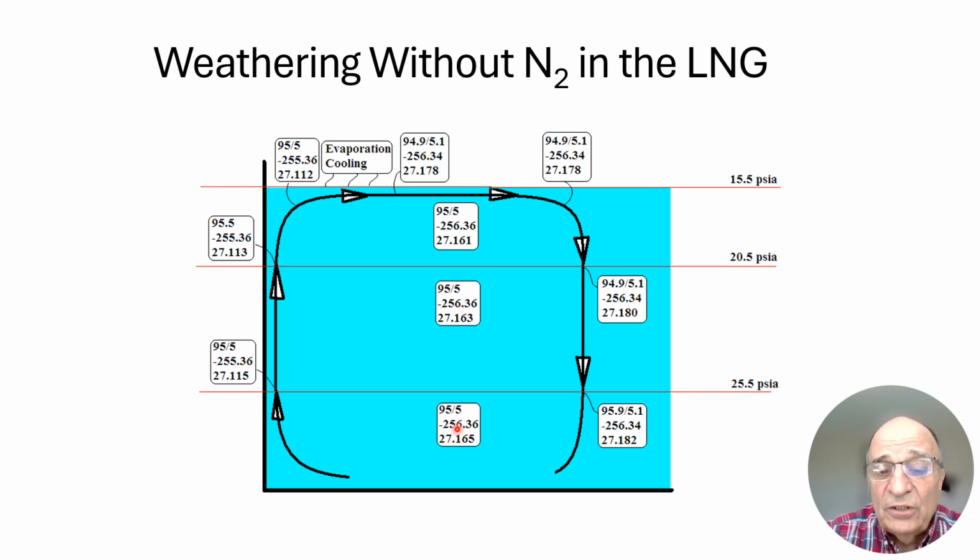Now I add 1 degree Fahrenheit, make it warmer at the surface. Where does heat come from? It came from the bottom as well as from the sides. And this 1 degree temperature increase has lessened the density. How did it lessen the density? Well, the LNG liquid expanded. So the density becomes less and this becomes lighter than its surrounding LNG, and therefore it rises, causing a convection current. And it rises until the evaporation takes place at the top.